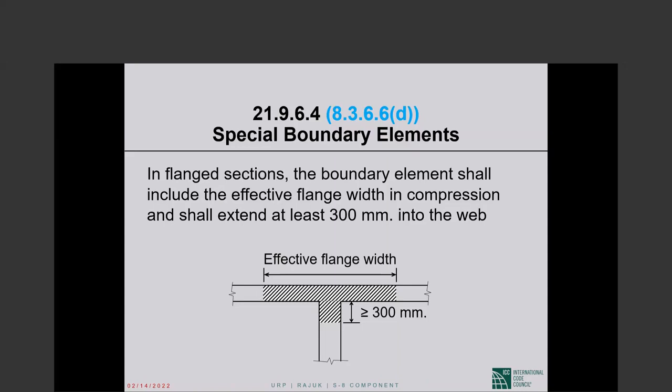This question I didn't understand. I'll read it out to you. Maybe you will also feel the same thing. If significant compression is developed by a beam resting at the midpoint along the length of the shear wall, should we design that point by providing confinement reinforcement like a column, or should we consider the stress to be distributed throughout the wall length?